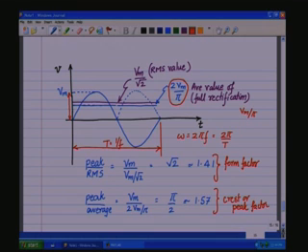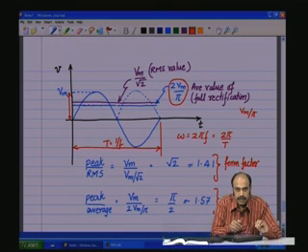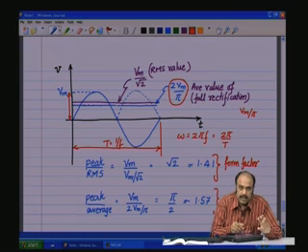The RMS quantity is something that relates to the power, equivalent power producing or power generating quantity. See, the power is in terms of voltage square by R, or it is amp square into R. That equivalent voltage is called the RMS voltage.